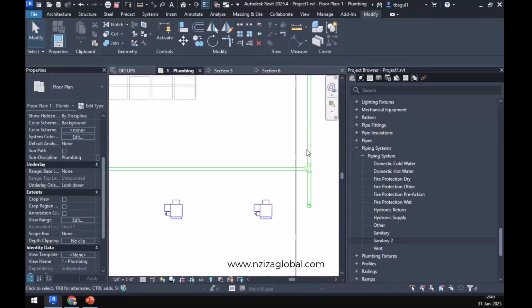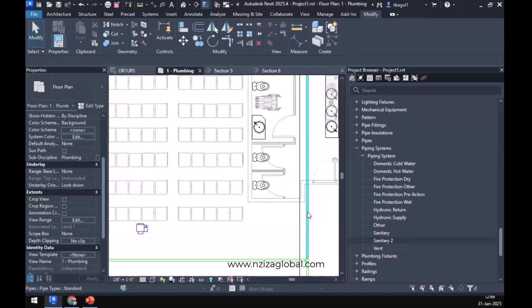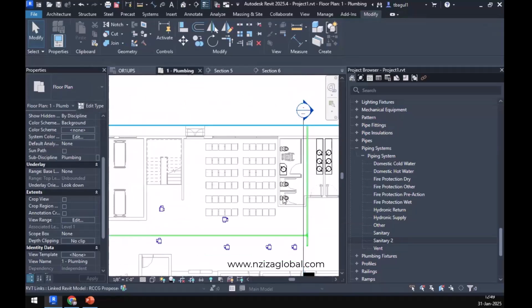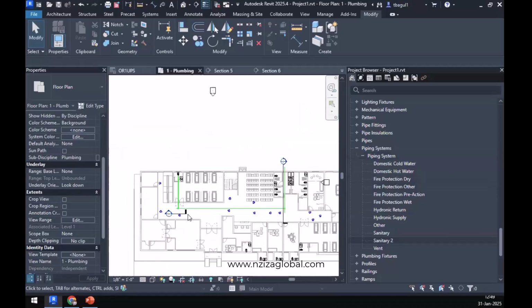All right. Now still we have 7 DFUs over here, right? Now, if you add this, how much DFUs one water closet we had? 6, right? So now 7 plus 6. The total DFUs after picking up the soil from this will be a total of 13. Making sense till now? All right.